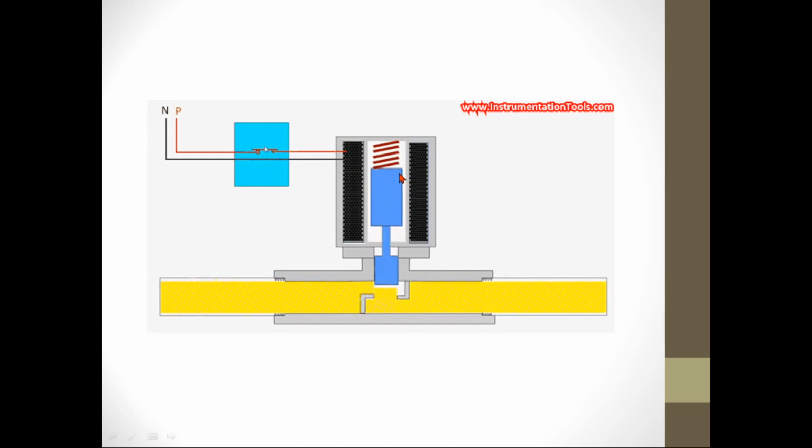Again, for a solenoid valve to work, the coil must be supplied with the rated voltage. Once supplied, the plunger will be attracted by means of magnetism, thereby allowing the passage of air from the inlet to the service port. How to stop the passage of air?